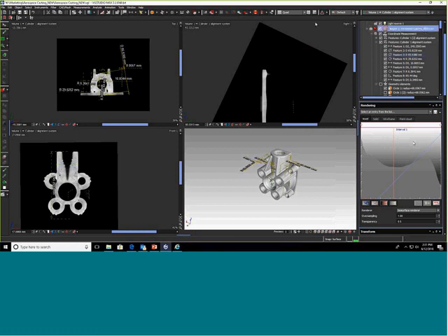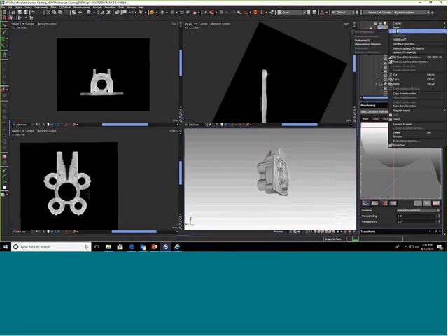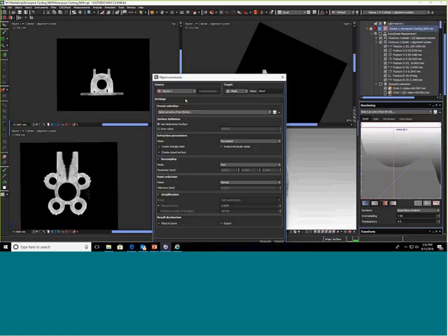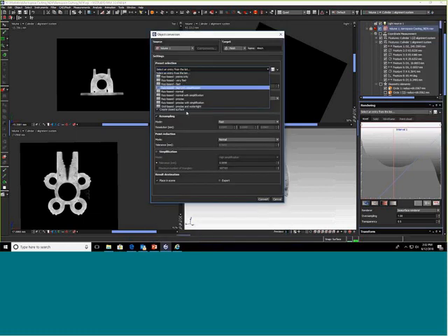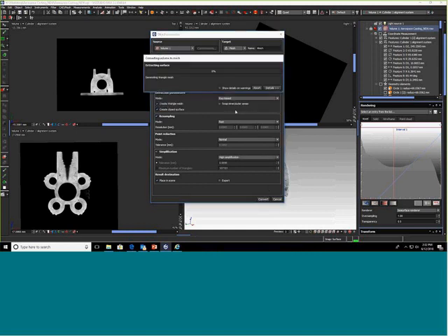Okay. For those folks interested in doing reverse engineering, the beautiful part about computer tomography is, once your part has been scanned, you can easily create an STL from it. So we're going to do a fast little STL. Basically, you can create a full STL containing not only void information, but all the geometrical information as well.